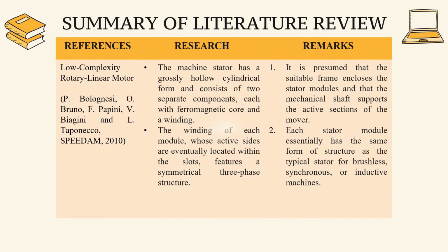The next study is about the low complexity rotary linear motor. The machine stator has a hollow cylindrical form and consists of 2 separate components, each with a ferromagnetic core and a winding. The winding of each module, whose active sides are located within the slots, features a symmetrical 3-phase structure.